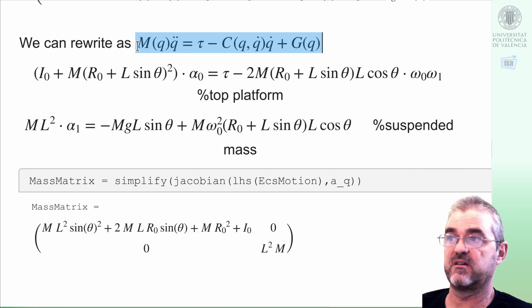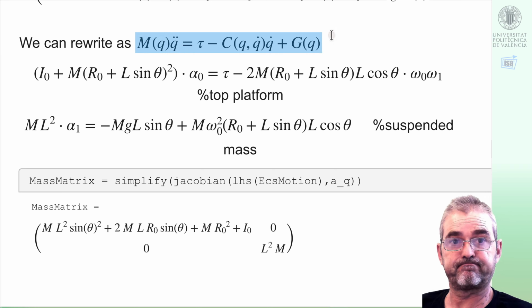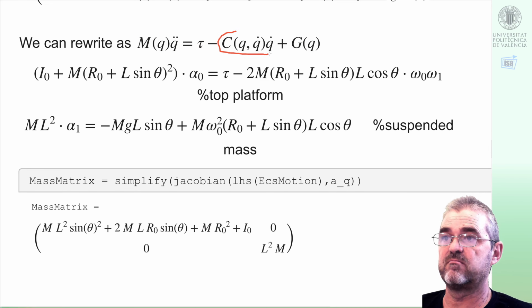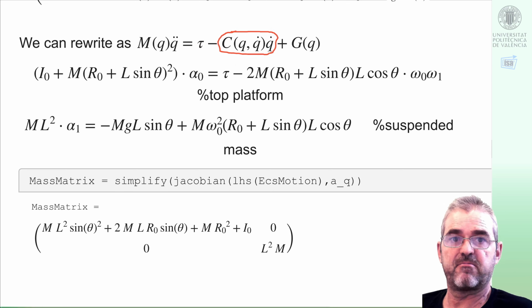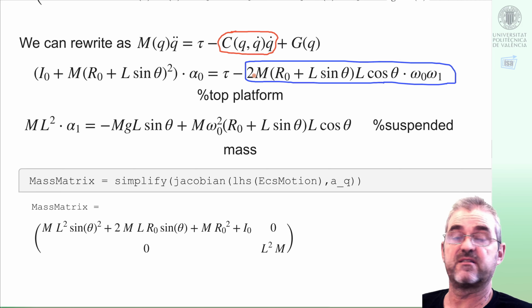Well, the thing is that we have a mass times acceleration, or inertia times angular acceleration, equal to some balance of torques, forces, whatever. In this way, we have the external torques. Then we have some Coriolis or centrifugal force or things like that, usually depending on the squares of speeds. This coupling term depending on this product of angular speeds affects the platform.